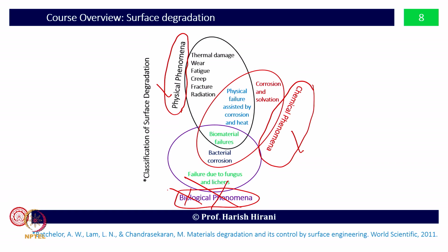And of course, we will cover all the topics, because in physical phenomena there is the thermal aspect, since wherever we are increasing energy it will come into this relation. There is a physical phenomenon sometimes called the wear phenomenon, even fatigue, which is surface fatigue, which may lead to wear also. It is not necessary that wear occurs only because of physical phenomena under very high load. Quite possibly the surface fatigue causes some spherical particles, which increase the possibility of wear, or maybe increase the pits, and that causes wear also. So, these phenomena may be interrelated also.